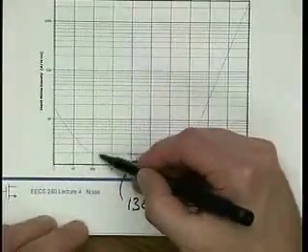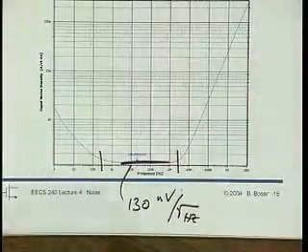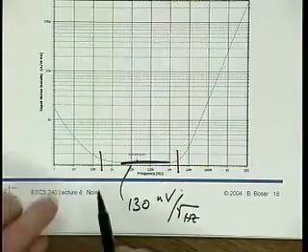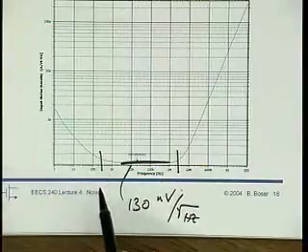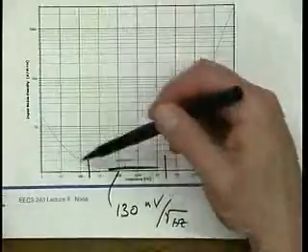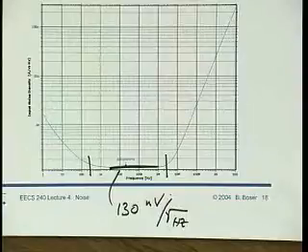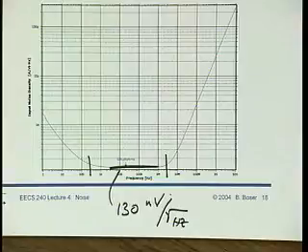what's actually happening here? Why does the noise suddenly go up like this? Well, the reason is that this additional noise here is really noise from the transistor and RL. Those noise sources contribute noise to the output of the circuit, even at very high frequency.